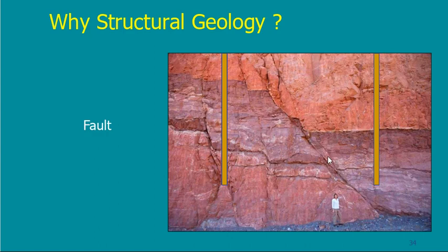If I find that this is a fault, then I would have to go to a more specialized person, maybe a geologist, to tell me: is this an active fault, is it not active, and so on. And even if it is not active, I should avoid this fault. But being active or not active will tell me how far I should go away from this fault. You do not put your building on top of a fault, active or not active, because if it is not active now, it may be active in the future.